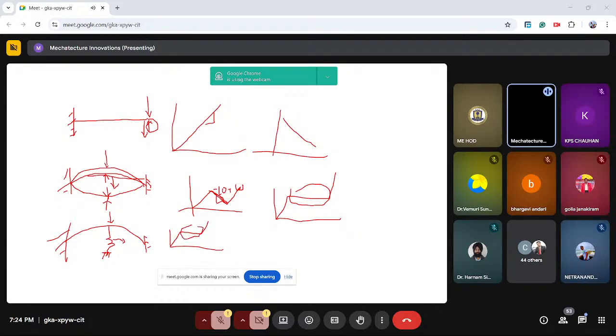This zero stiffness region is utilized in vibration isolation. To keep it short, in order to get better vibration isolation, the fundamental concept is that I have to reduce my natural frequency below the excitation frequency. For example, if the excitation frequency is 100 hertz, my natural frequency should be less than 100 hertz. The more I reduce it, the better the isolation. If I keep the natural frequency at 50 hertz, then when the excitation is 100, my body will isolate. But if the excitation is coming at 10, my natural frequency is more than the excitation, so isolation will not happen. So I have to keep reducing.